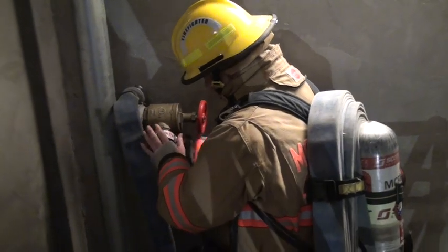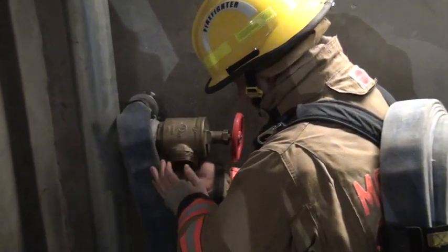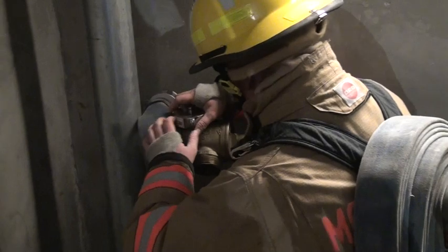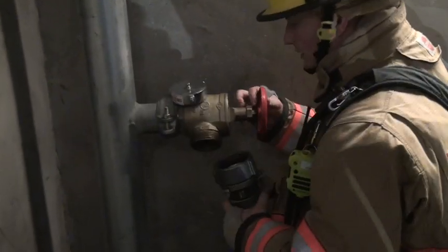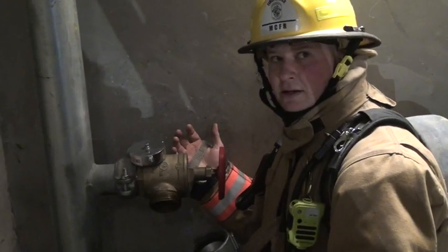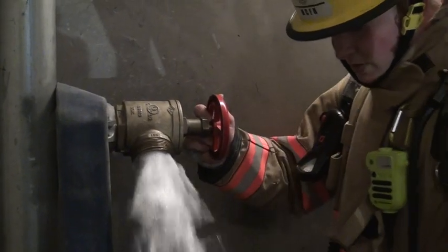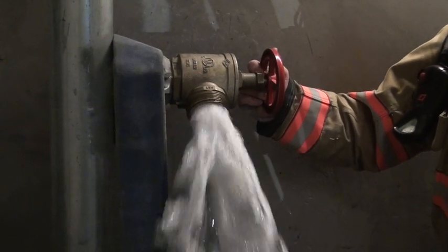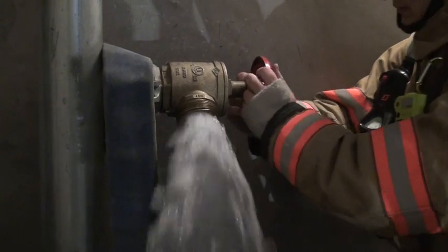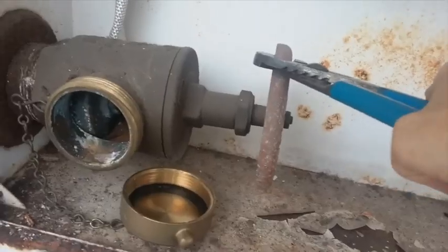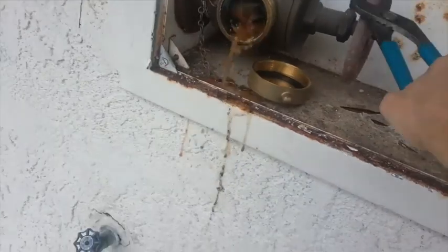Connecting to the floor below is a NIOSH recommendation due to the possibility of conditions deteriorating on the fire floor prior to having the hose line in service. It is important to flush the riser prior to using it. This helps remove any corroded metal or other debris from blocking the connection or the nozzle.